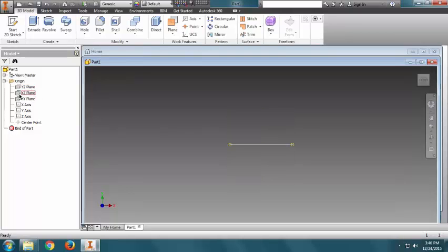Let's select any of the planes first. It depends on what figure you're trying to draw. Like if you're drawing something which is fixed to a wall, you use the YZ plane, just like a wall clock, where the clock is affixed to it and you're watching something in the front view. And if you are drawing something like a table lamp which is on a base stand, then you need to draw it on an XZ plane so that you'll have the front view easily visible.